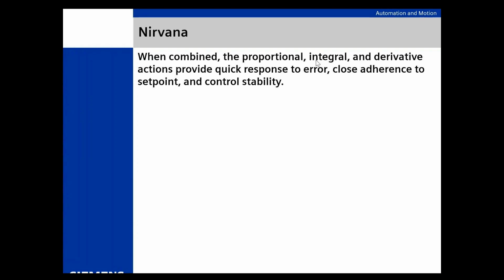And the dead giveaway is you shut the valve and you shut the flow off, and it's flowing 400 GPM, 500 GPM, and it's still flowing 500 GPM. And it sits there, and now it starts to kind of tail off to zero. It does that because somebody's piled the deadband on it. Because somebody wanted to see a flat line. Well, I'll give you a flat line, but it's going to cost you control resolution. Like I said earlier, it always costs you something. That's what it costs. And trying to explain quarter wave decay to somebody in operations, well, good luck with that. They just want to see their flat line.